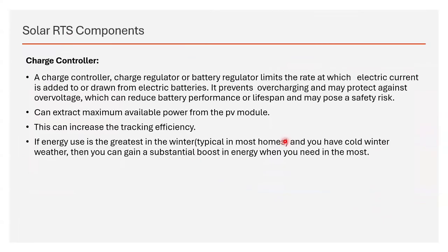Otherwise, what happens if the charge controller fails to operate near Pmax? Then either there will be a higher voltage across the terminals of the solar PV cells, or there will be a voltage drop and less power.